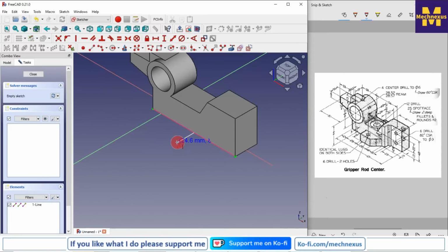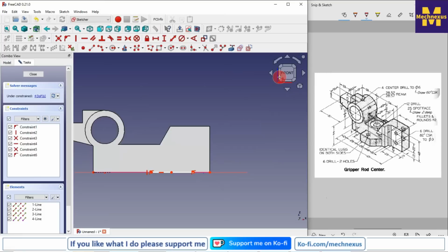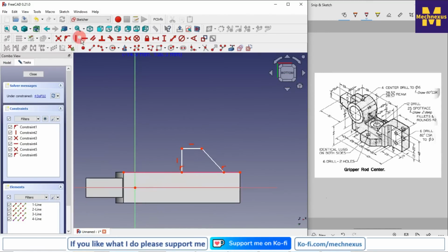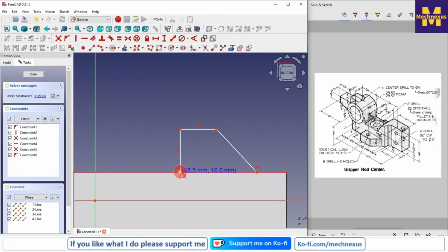So this will be vertical and horizontal and join with this, and from the orientation I will switch to the bottom face, and I will select the line tool and close my profile.